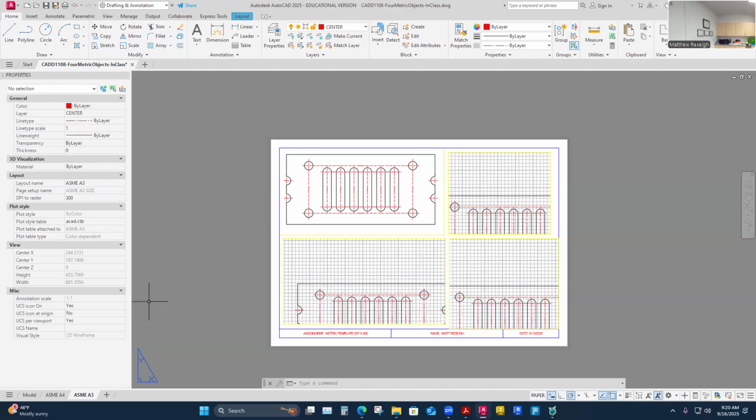But the way I actually did mine is I adjusted that one so the bottom is just at 6. So all of these have to be 6 millimeter. That's the equivalent of 0.25, a quarter inch, 6 millimeter metric. It's not exact, but what you'll find is a lot of metric will go to the whole millimeter, not the decimal millimeter, like in a lot of conversion measurements. The text size essentially is 1.125 in inches, which is just 3 millimeter in metric. Same with here, I just do a 6 millimeter extension. So you can adjust all these to 6.